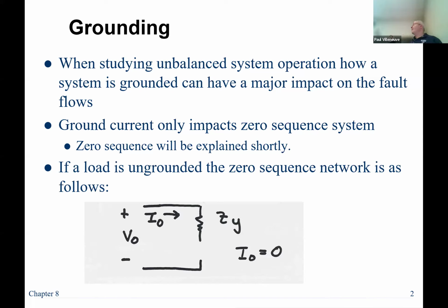Because if I have a system that is ungrounded and that first ground occurs, no big deal, right? Nothing happens. I don't get electrocuted because there's no complete path. The problem becomes when a second ground occurs. When the second ground occurs, now you have a lot of fault current and then you trip. The reason why you want to have a grounded system is it allows you to detect that a ground has occurred on the system because it causes a trip.